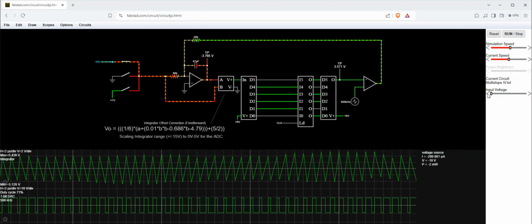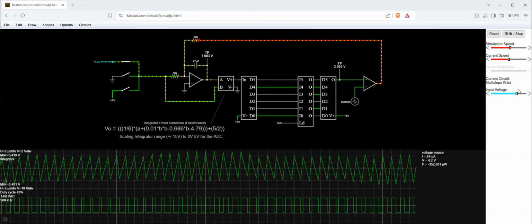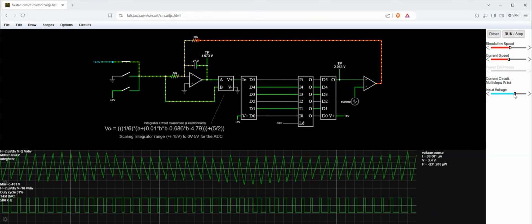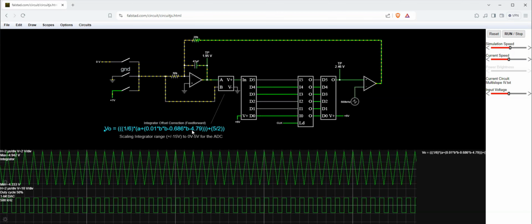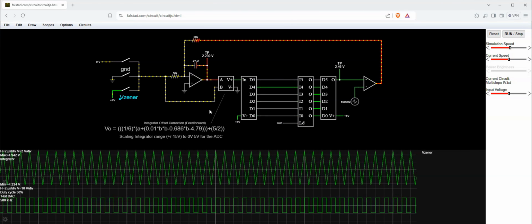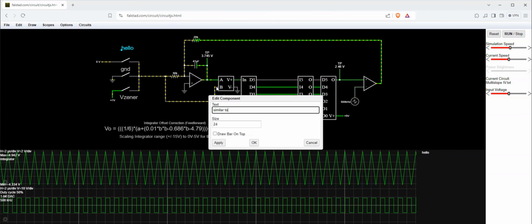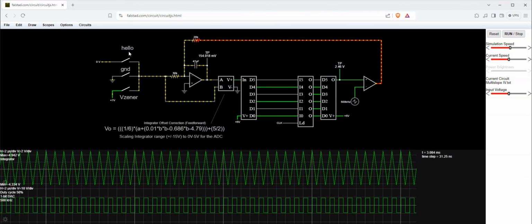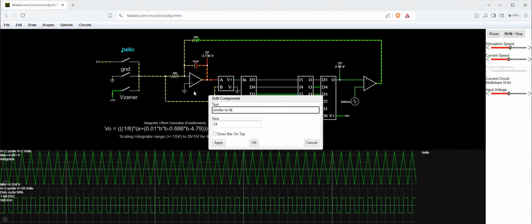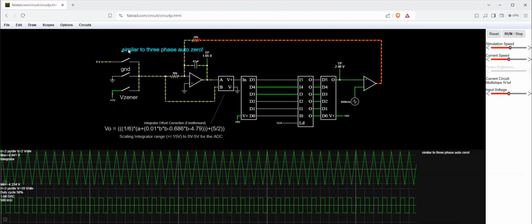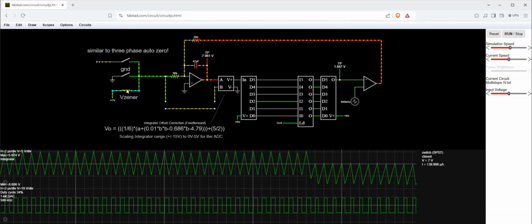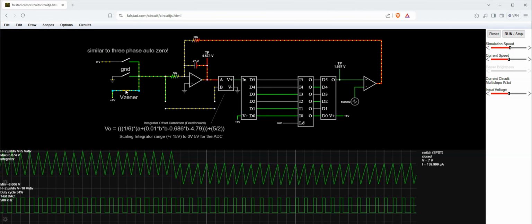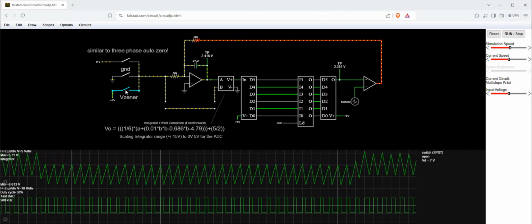This offset can be compensated for by calculating an appropriate transfer function that tweaks the ADC input based on the input voltage. In this case, we would need a 3-point calibration to determine the correct feed-forward function. Available to the ADC are two absolute references, ground and the Zener reference itself. Those 2 points could deliver a good linear approximation which centers the integrator to a large extent. However, I'm not sure how the calibration algorithm is implemented in Multislope 4.